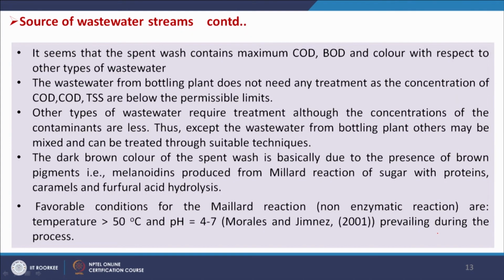So, it seems that the spent wash contains maximum COD/BOD and color with respect to other types of wastewater, and the wastewater from the bottling plant does not need any treatment as the concentrations of COD, BOD, and TSS are below the permissible limits. Other types of wastewater require treatment, although the concentrations of the contaminants are less. Thus, except the wastewater from the bottling plant, others may be mixed and can be treated through suitable techniques.